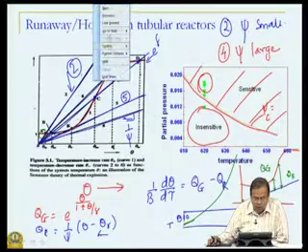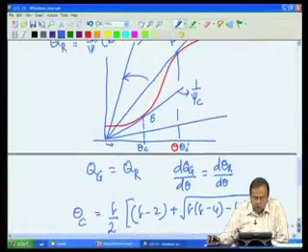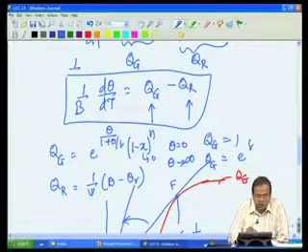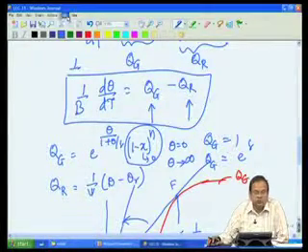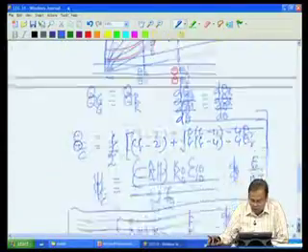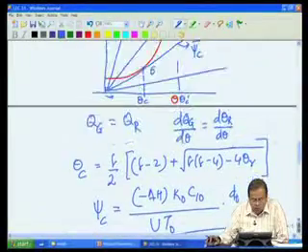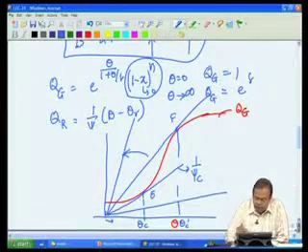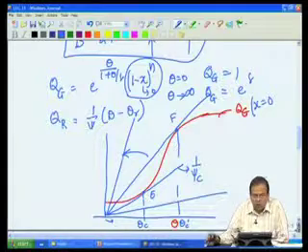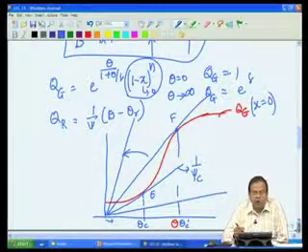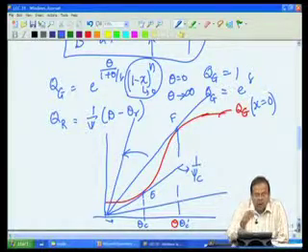Now, going back to our example, we said that we neglected the reaction altogether. Okay. So, in plotting this, we said that this term is unity, this particular one. Now, let us just qualitatively try to see what will happen as the reaction proceeds and how do we get that hot spot. Okay. So, to do this, I am going to redraw this figure, but I just want you to notice the following fact. If this is my line QG with x equal to 0, then for a different value of x, my QR curves remain same, but my QG will have a lower value.